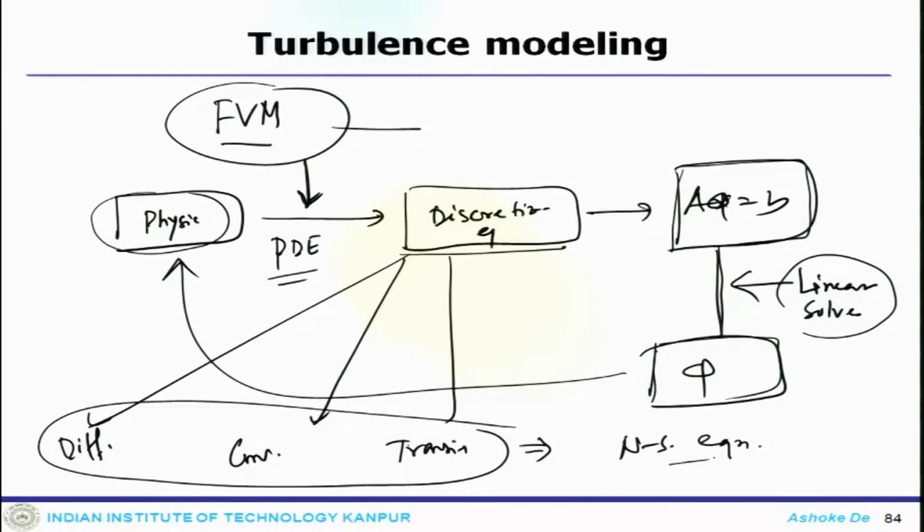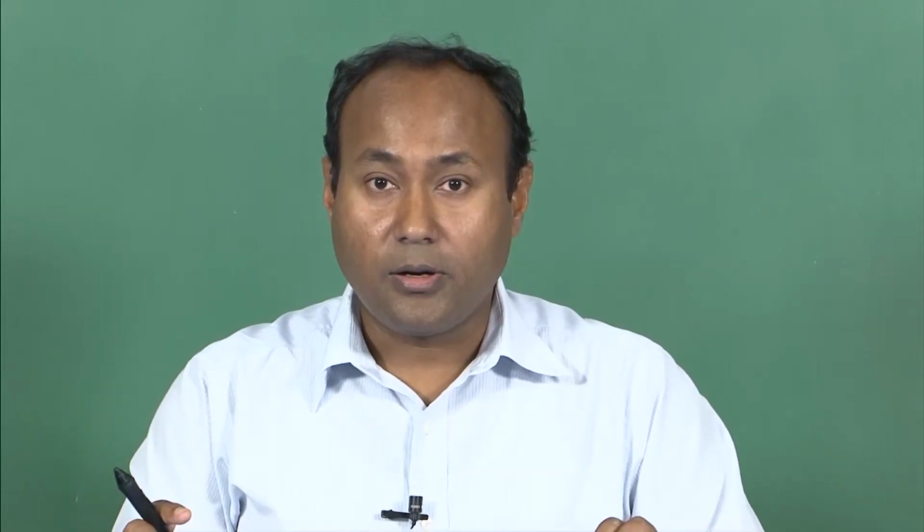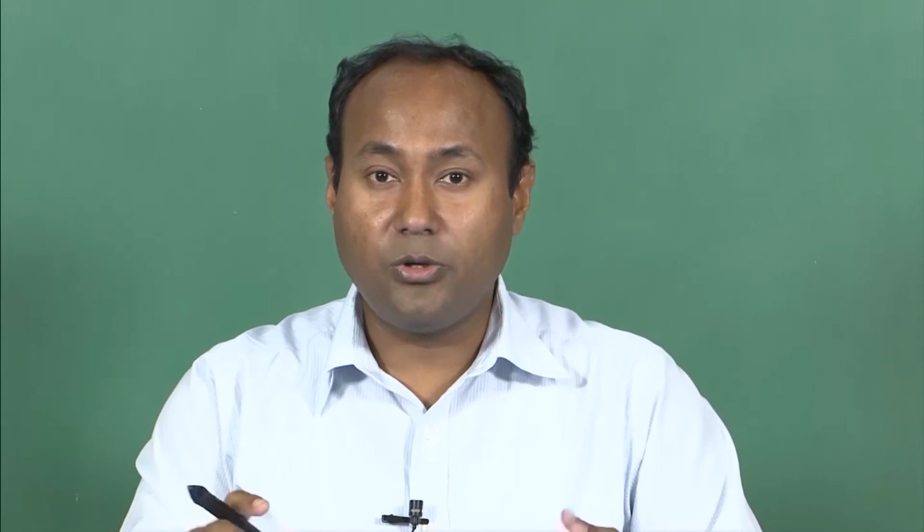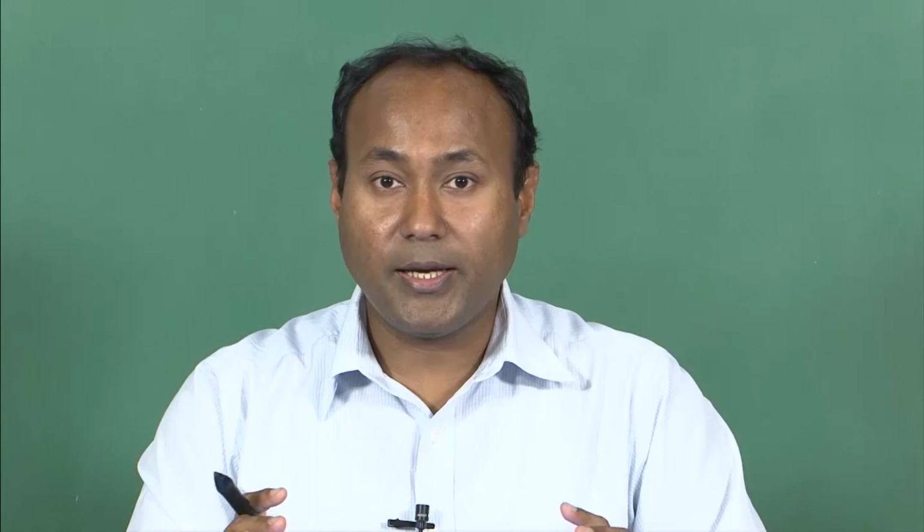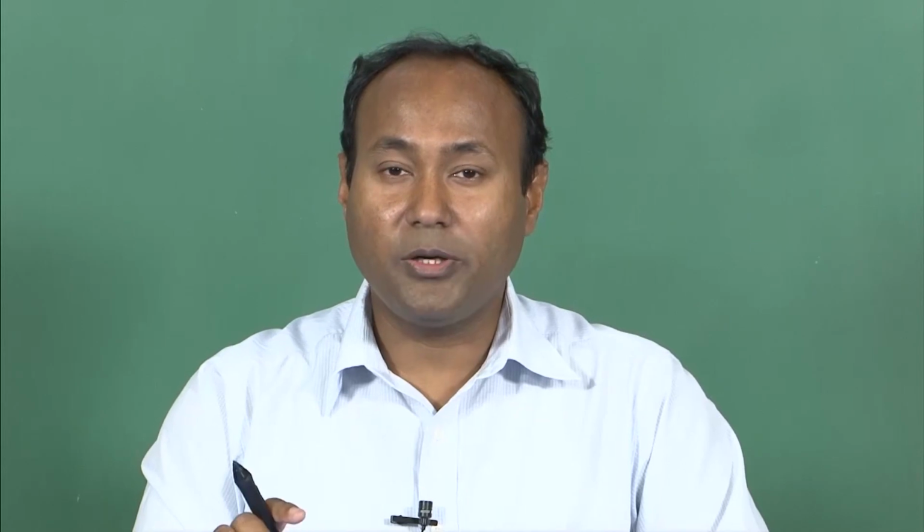When you go down to the fluid flow solver, we used our incompressible solver, then talked about the pressure-velocity coupling and the interpolation, and finally the SIMPLE family of algorithms. Then we moved to the compressible case, where again we discussed the discretization and boundary conditions, and finally we touched upon grid generation and turbulence modeling, and that concludes the discussion on finite volume. I hope it will be helpful to get started with the finite volume method.